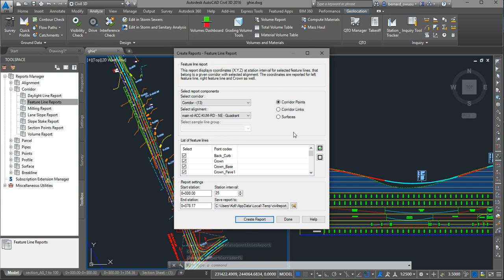Has something opened for you? Yes. Then you select your corridor name. My corridor name is Accra Kumasi Road Corridor. Have you selected it? Yes. Then the alignment automatically comes. Then please watch, change this one to corridor lengths. Instead of corridor points, change it to corridor lengths.